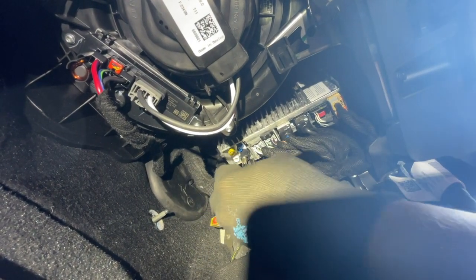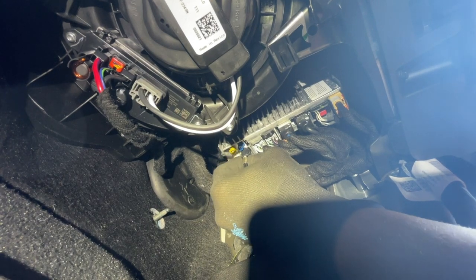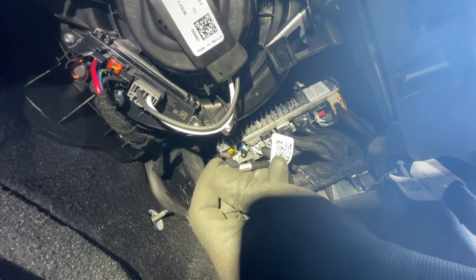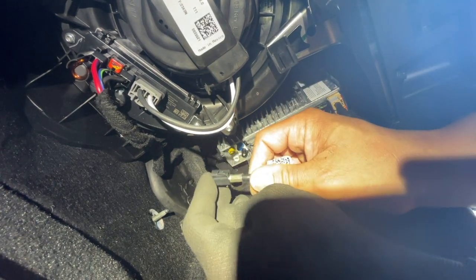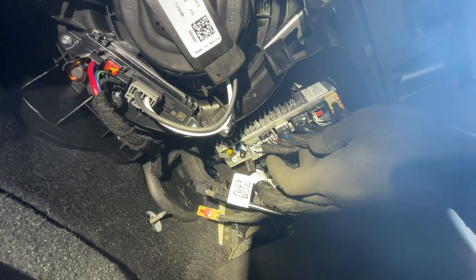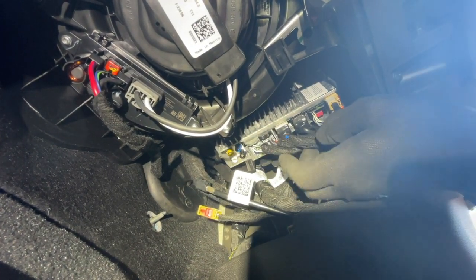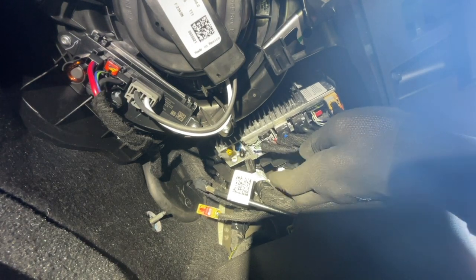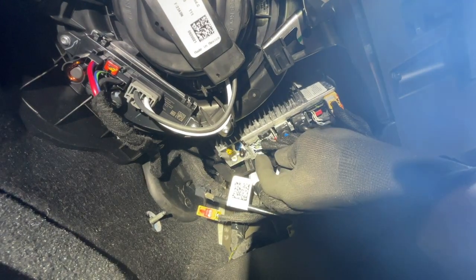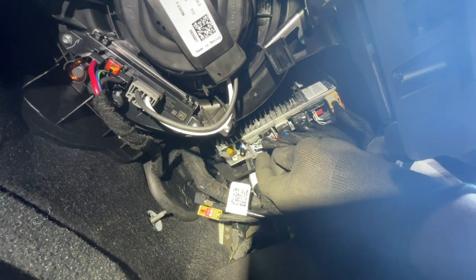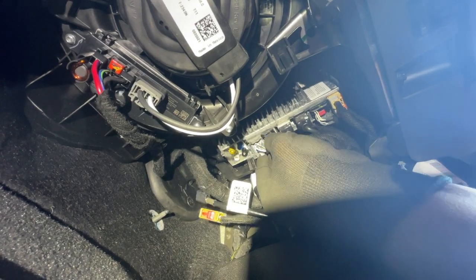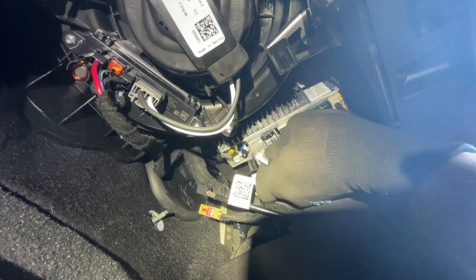Next is this black cable. On the right side, there's a tab here you can push in and carefully unplug. And there's a release tab right there. The next 2 connectors will be this gray and this black connector. Now these have a connector lock here on the back side, and it looks like it's a clear CPA. So if you can get your fingernail underneath it and pull it down, go and pull it down and then push in to release.